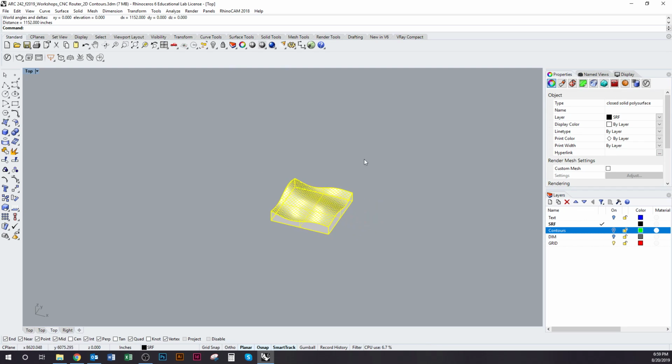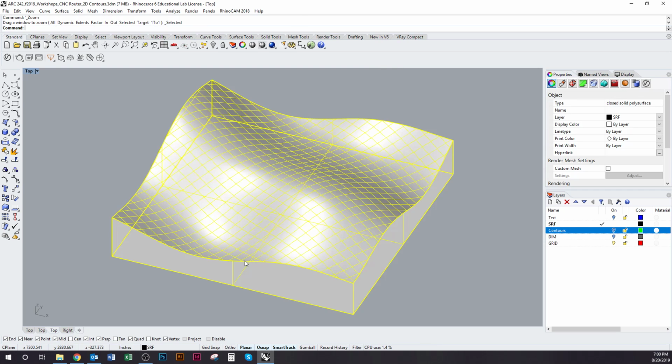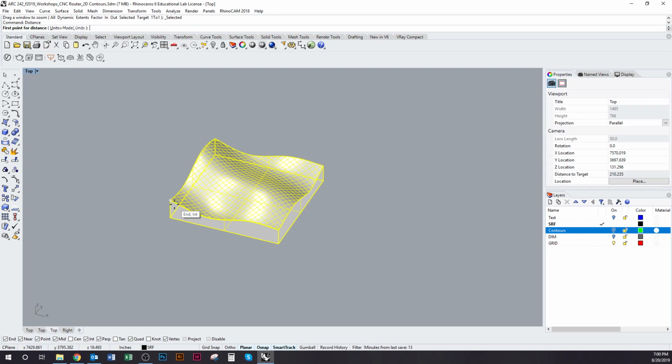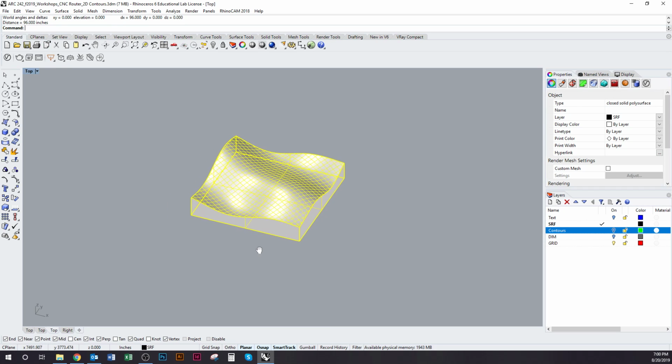So in order to go down to the scale I need to make a model of it, let's say the scale we're going to use here is 1/16 of an inch equals a foot. And what I'm going to do is scale it. So I type scale in the command line, choose a corner point, and first I want to scale it from feet into inches. So I'll type 1 divided by 12, 1/12. Press enter, and now you can see if we measure the distance again, we just scaled from feet to inches. So now our tile is 96 inches by 96 inches.